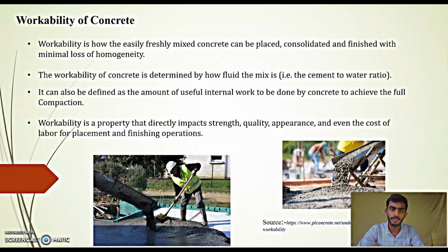In today's topic, we will learn about the workability of concrete, how the workability affects the concrete, and the factors affecting workability. First, we will learn about the workability. Workability is how easily freshly mixed concrete can be placed, consolidated and finished with minimum loss of homogeneity. It means how the concrete can be placed at the construction site or in any other construction work, without compacting and finishing, how the concrete can be placed easily in the beam, column or any other work.